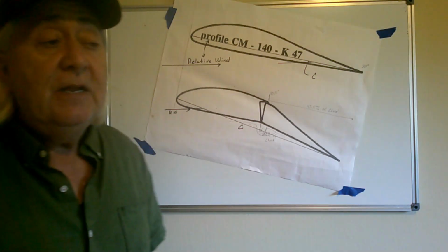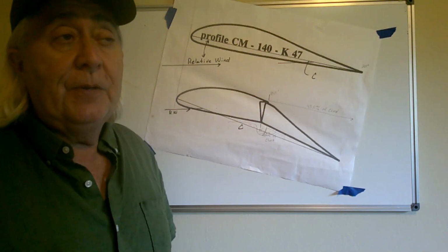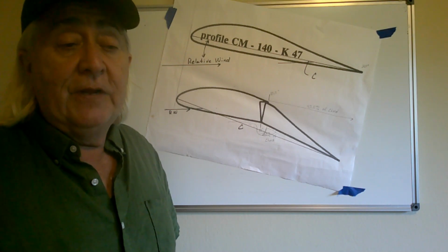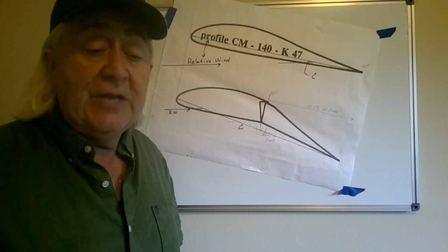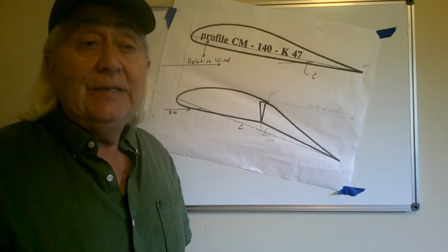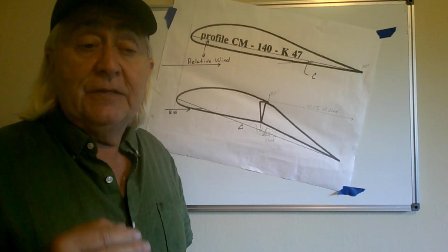So Steve's saying that if you had a sudden flap deployment on this, just the pitching moments that are involved and running out of elevator would cause a rapid nose down, as would a stall. And what I've shown you with the data is that it's most likely the stall.